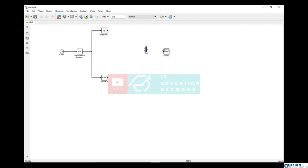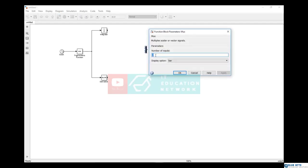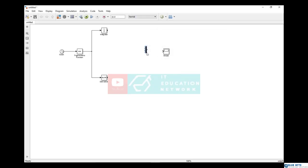You will see that it accepts several signals and has an output. By double-clicking on the Mux, we can know how many signals it receives. You see the number of inputs here, but because we want to show 3 inputs here, I set it to 3. Now as you can see, the inputs increase. One of the Mux inputs is related to the integrator.